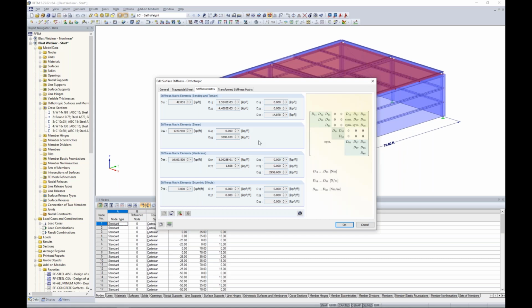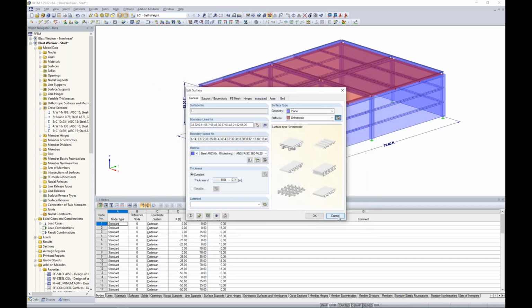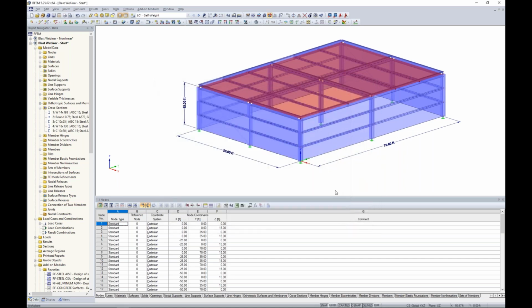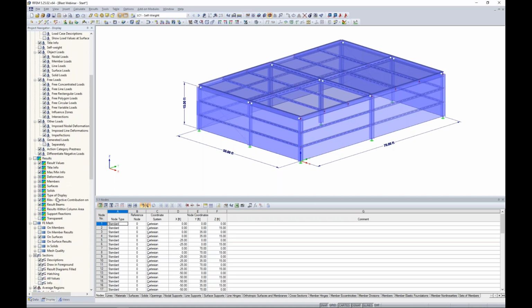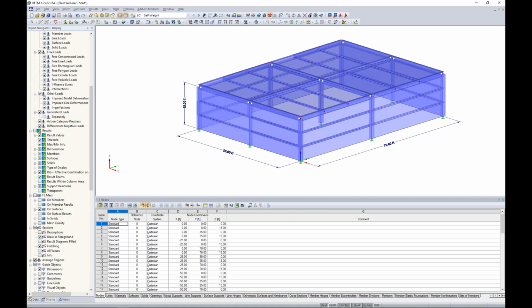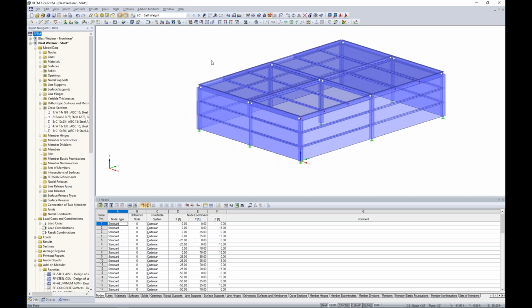So this is definitely going to add a lot of lateral stability to our structure at that roof level. And I went ahead and used it for the wall elements as well. All right, so that is a basic overview of our surface elements as well as our members. So under my display, I'll go ahead and turn off my dimensions here, and let us discuss the loading.